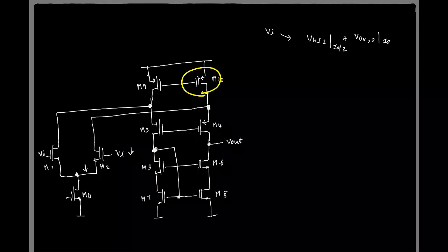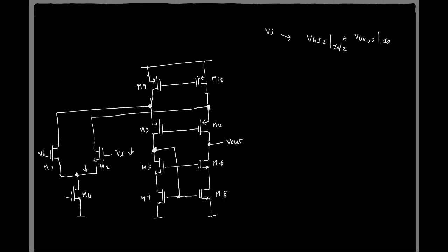No, this is the drain, right? If I keep increasing this, I mean the drain is, let us say, fixed, it doesn't change. And by the way, with respect to the saturation region calculations, only gates and drains matter, right? So if I keep increasing the gate voltage, the NMOS transistor will start to enter triode, so this guy will have issues.